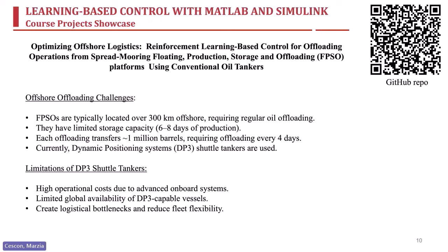And this is done normally with dedicated shuttle tankers, which are called dynamic positioning systems. However, in addition to the large operational cost of these dedicated shuttle tankers, their availability is limited. We don't have so many DP3 capable vessels available globally.